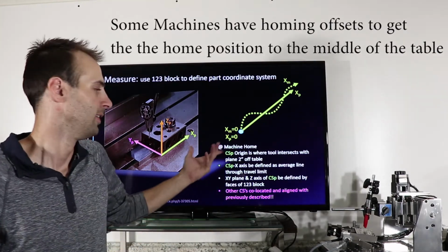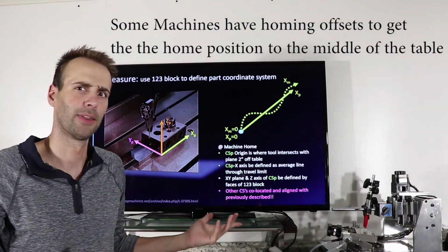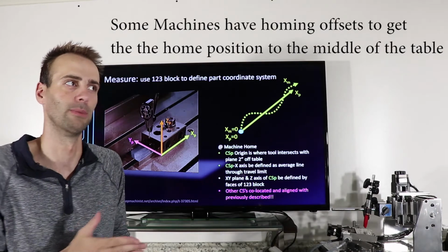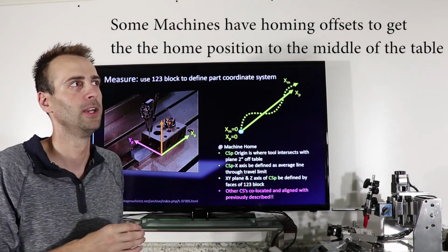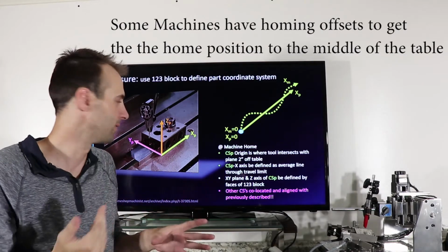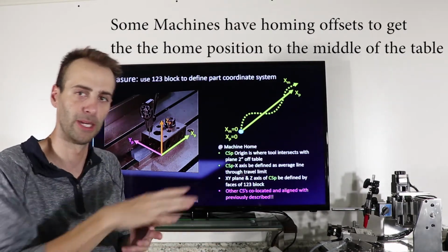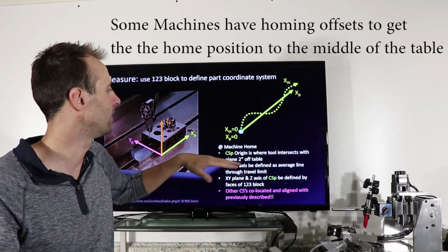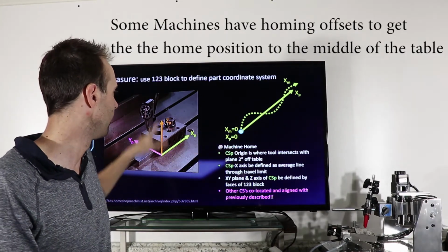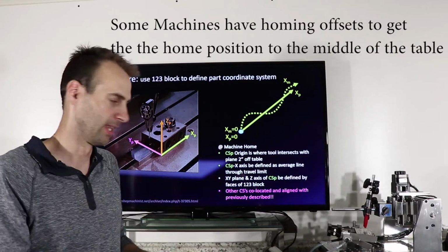And then for things like G-code, I don't think you have a choice but to use machine home as your starting point, because when you reset that thing or run the program, it kind of goes from 0, 0, right? Unless you have a homing operation program or whatever, but just make things simple for yourself. When the machine's at home, that's where you want that, okay?